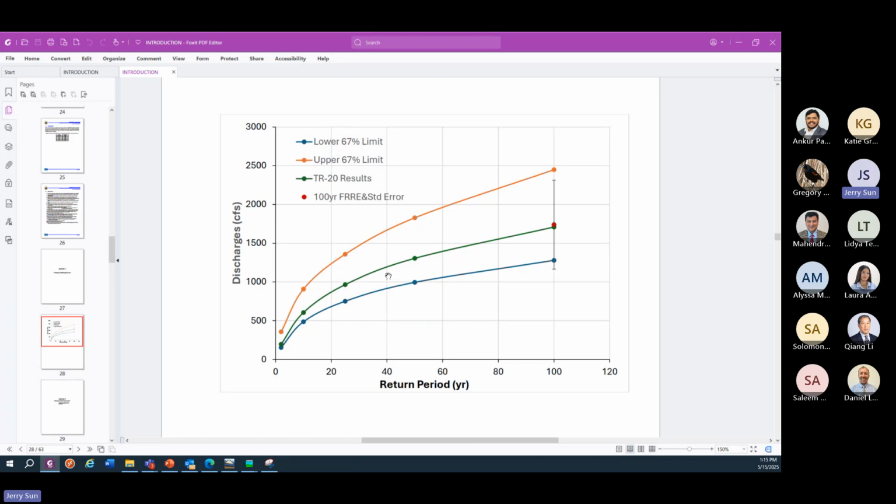So Greg, this green line is showing our modeling result, and the up and down lines show the regression equation. The Maryland hydrology panel developed it and we are using it. As long as our green line is within this band of blue lines and that orange line, we are okay. It could be a little bit more or less than whatever discharges we have computed.